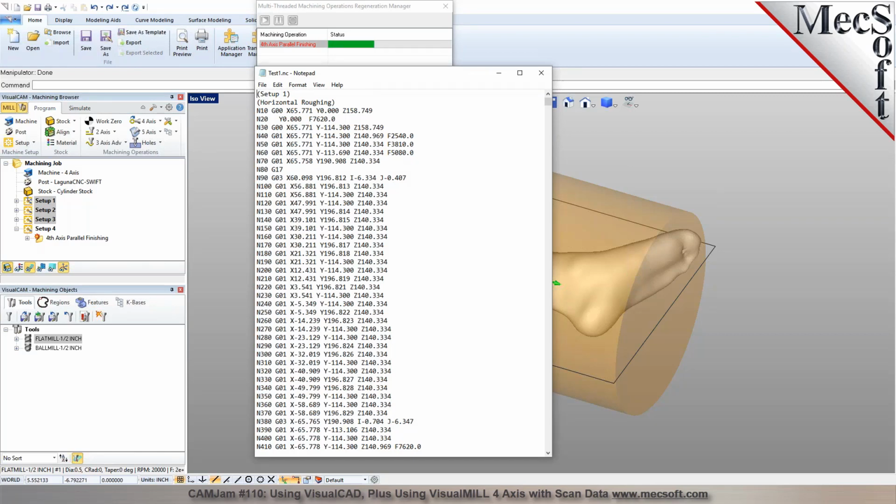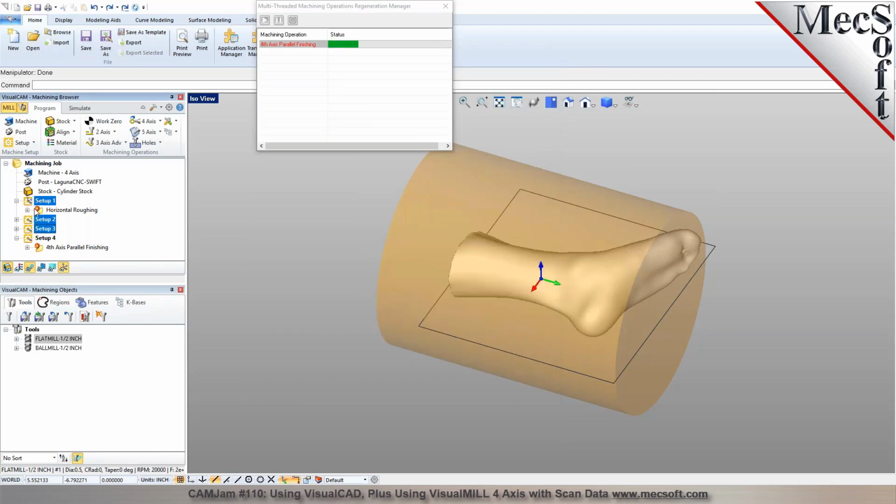So probably 5 minutes to generate your G code from the time you pull in an STL? I would say, yeah. You can also optimize your workflow here. You can save all of these to a knowledge base. So when you have similar parts that you want to machine, you bring in the part, orient it, define your stock, and then load the knowledge base and generate the toolpaths for it. So it's going to take less than a few minutes.